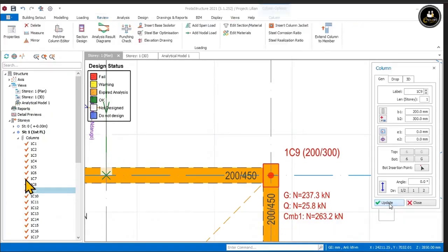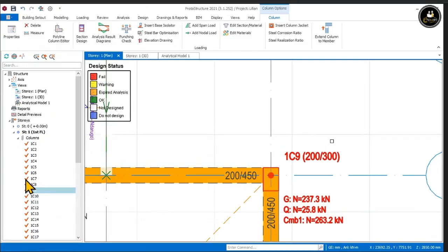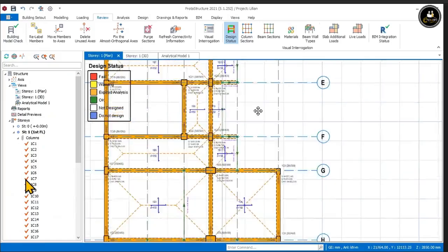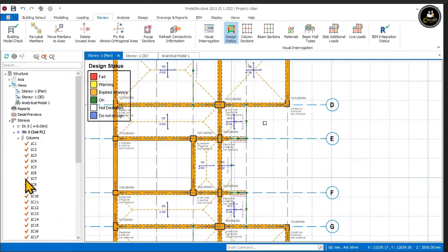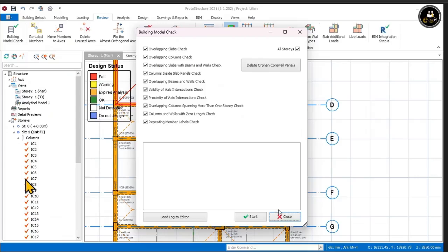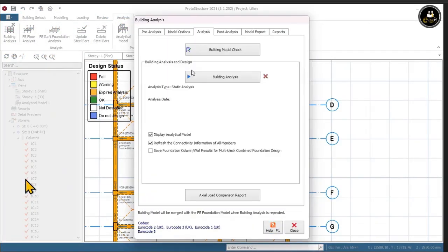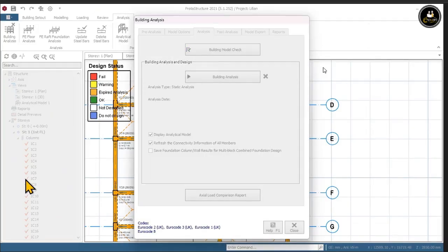Again, there are some other minimums that you should not go below. You can also check on its eccentricity, reduce it to 50. Okay, I think it's fine. So there are some other minimums that we ought not to go beyond, like you can't have lesser reinforcement. Though the utilization ratio might sometimes show you 30% or 20%, you have given it the minimum column size under the reinforcements.